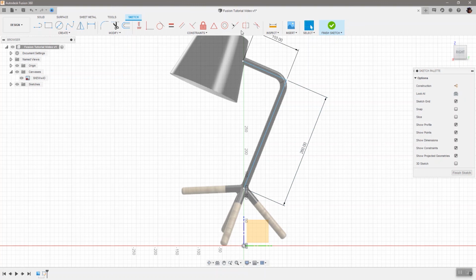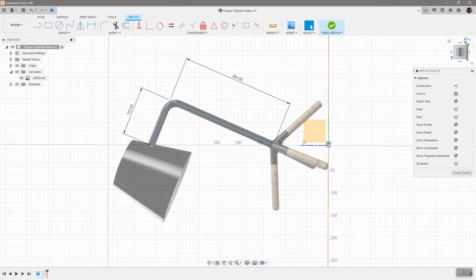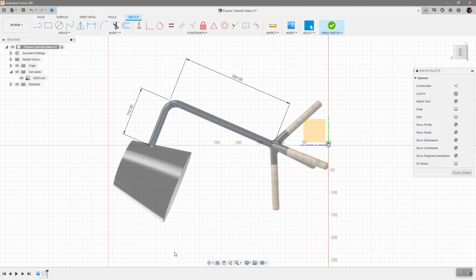Now you might be asking, why do we call this horizontal and vertical? Because horizontal and vertical are very different things, right? Well, that's because the idea of horizontal and vertical in CAD is very esoteric. Right now, these are vertical to one another. If I go to my view cube and just turn this, now they're horizontal to one another. And as a result, we have one command for both. Many systems actually have two separate commands, and ours will always snap to whatever is closest. So if I was actually closer for some reason to, well, now vertical, prior horizontal, it would have snapped to there. So always kind of get it right.